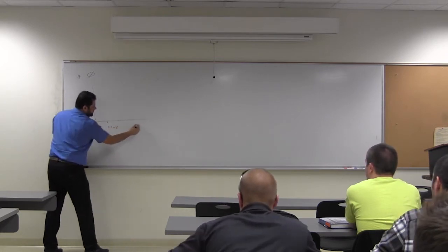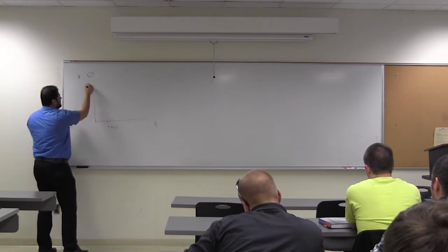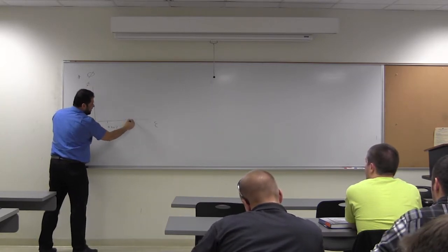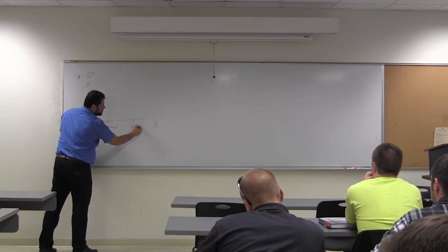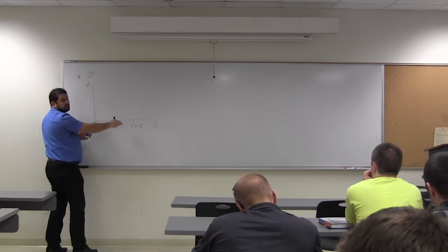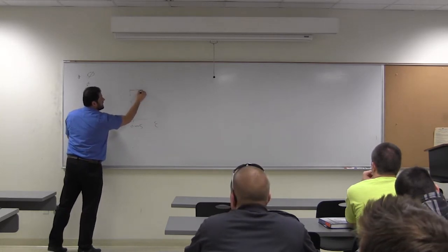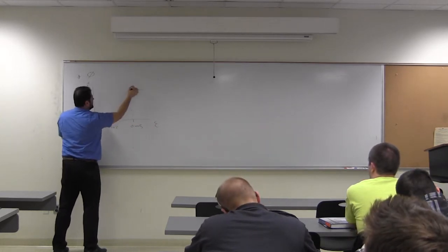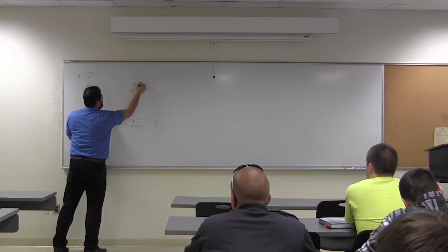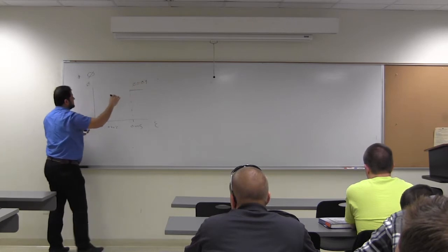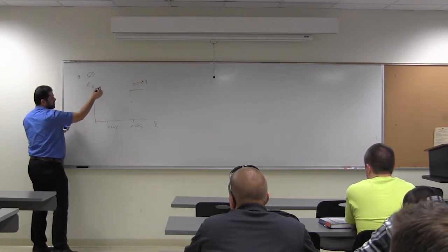This is the strain. And this is the Phi factor, the strength reduction factor, based on the strain in the steel at ultimate. If we have a strain more than 0.005, we're talking about tension control sections, right? Then the Phi factor becomes constant, equal to 0.9, and that's the maximum you can get.